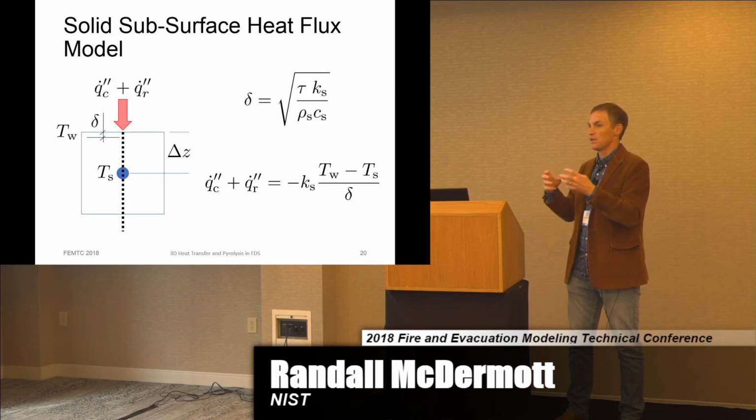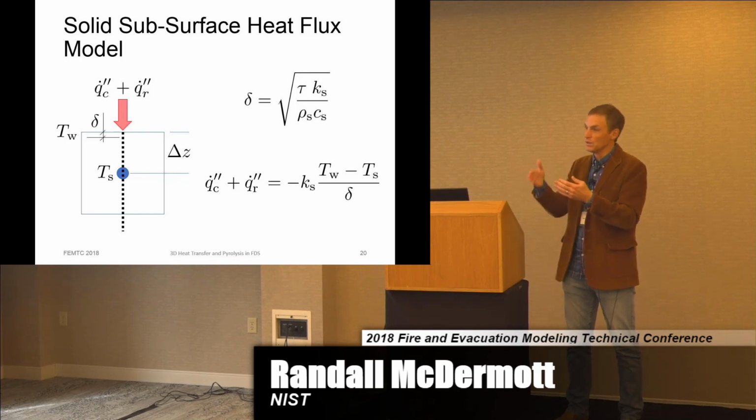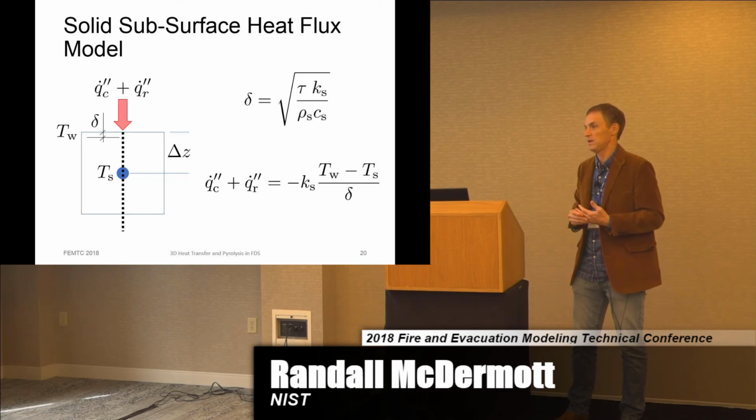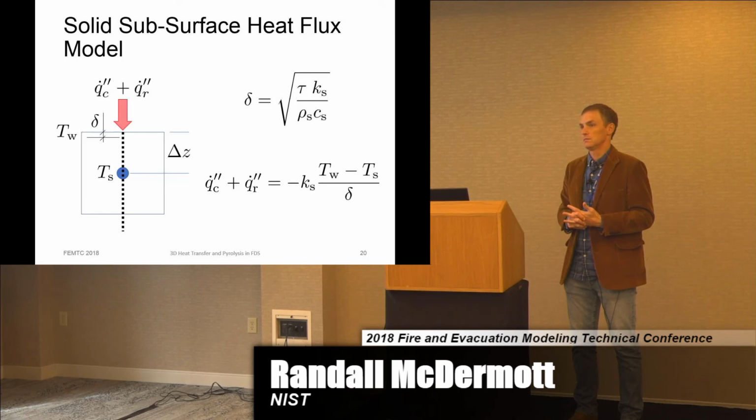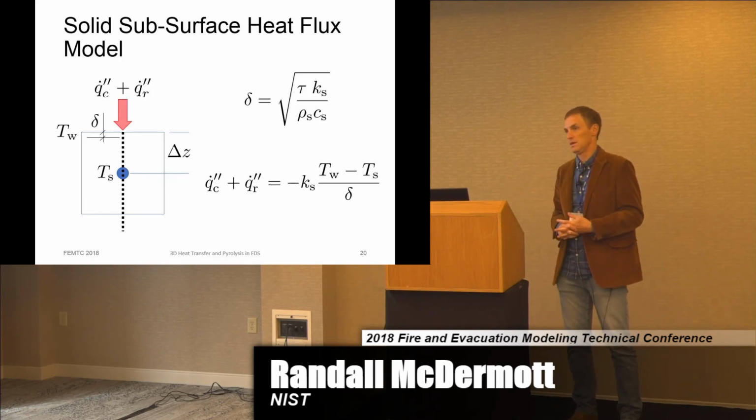He wants basically a thermal boundary condition to put into his finite element solver. And he says that those values are going to be different if you're only considering normal conduction in FDS. So that's where this all started, really. Right. Yeah, you don't want to recreate ANSYS. You just want to give it better boundary conditions. That's the idea there. Yeah.